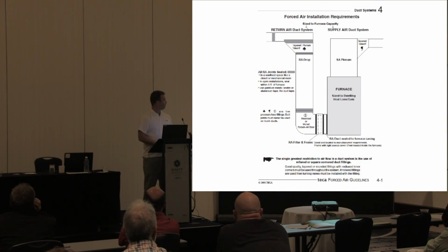So I'm sure David went over this, but I left a slide in there so you guys could see it, to make sure that as much as possible you try to use tapered fittings. We go over it because this is a duct design class as well. It's the same as anything else. If you need it to flow, the easier that it can flow, the less restriction you have, the less energy it'll take to run, and the quieter it'll be, like lots of things. So it's better if you can.